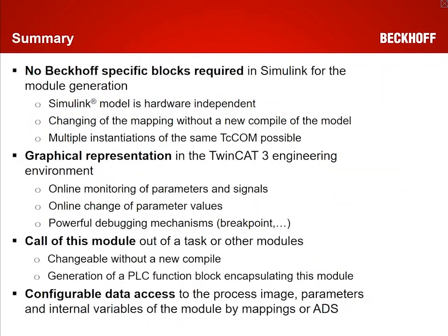Okay, so to sum up a little bit, all Simulink models that you have seen in this presentation are free of Beckhoff specific blocks. So this means that the Simulink model itself is hardware independent, so you don't make your model hardware dependent by integrating some Beckhoff specific blocks.